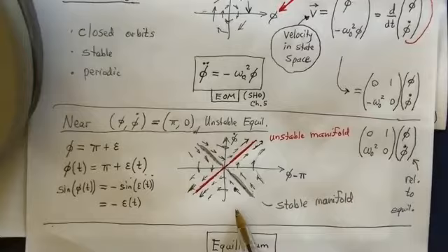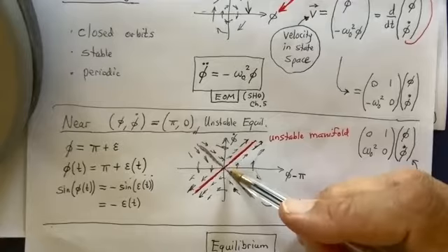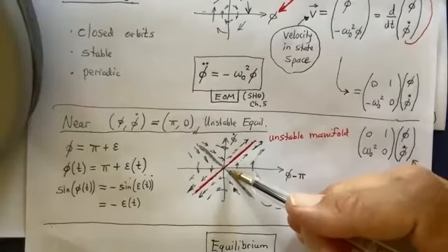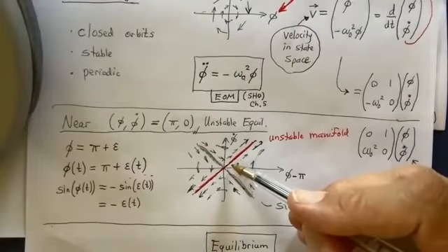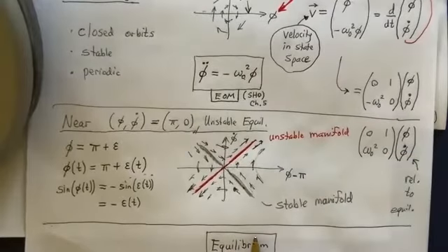You remember the dancing T-handle, these remarkable videos, and I did post several of them on B courses. When you have the angular velocity very, very close to the number 2 axis, the intermediate axis, then on the angular momentum sphere, again, we have a separatrix, and the vector field is very small when you're near that critical point. So the angular velocity vector and the angular momentum vector in the body frame get close to that number 2 axis. They reside in that territory for a while, and then they zip away and get faster and faster. So that was this remarkable motion that the dancing T-handle would appear to spin about one axis and then suddenly flip about. Rather quickly, it would flip about and then appear to spin about the other one.